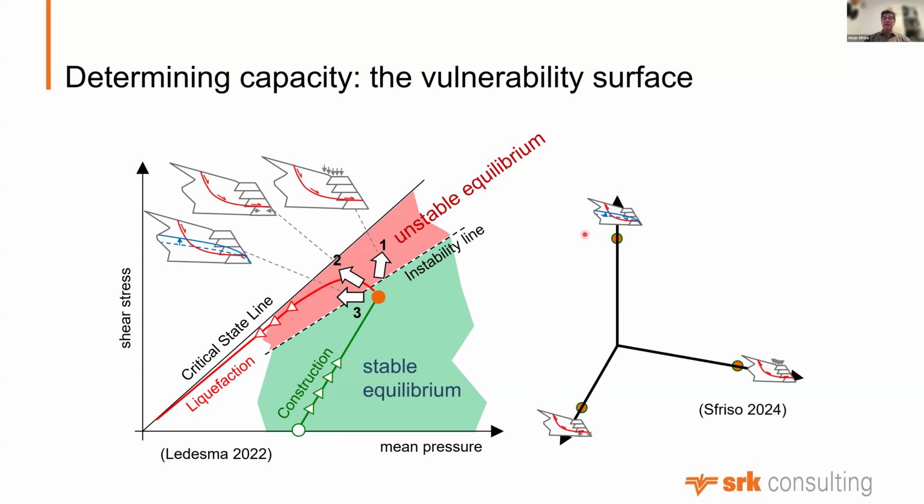And because these things don't happen independently, they may happen in combination. You also check for what happens when you have a small rise in the phreatic surface and a small load, and you end up computing which value triggers flow liquefaction with this combination.